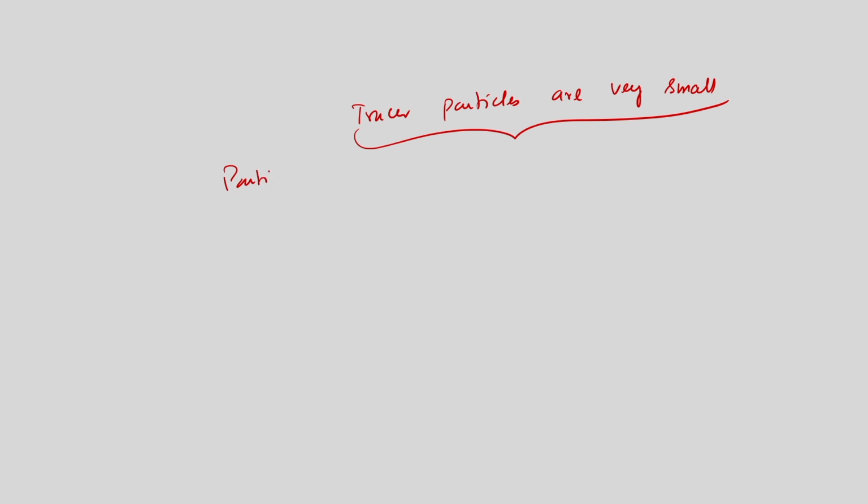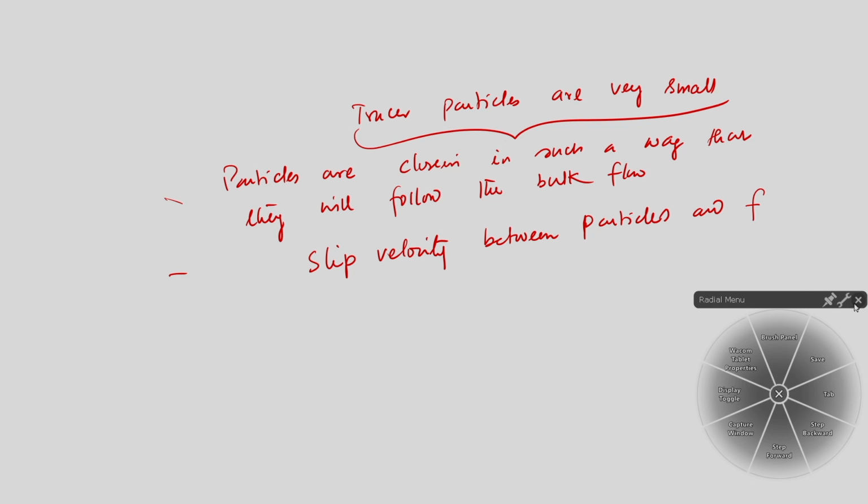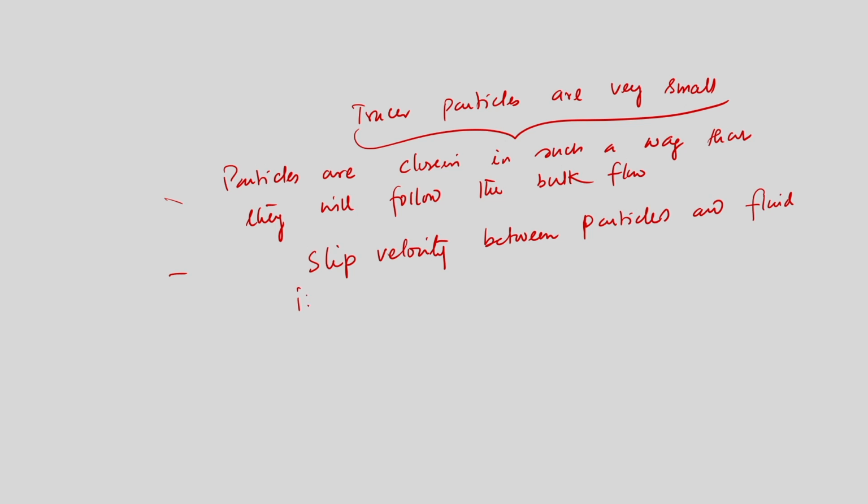The particles are chosen in such a way that they will follow the bulk flow, and the slip velocity, the fluid slip between the particles and fluid, is negligibly small.